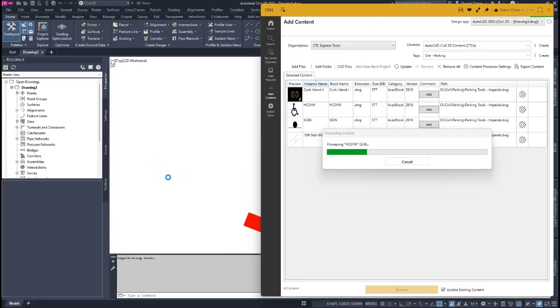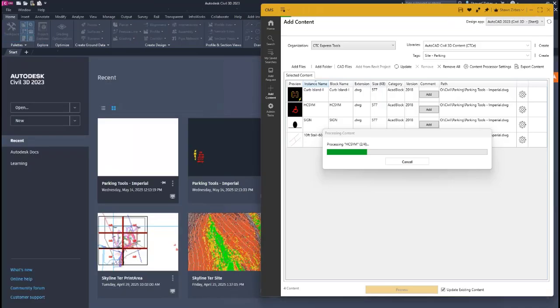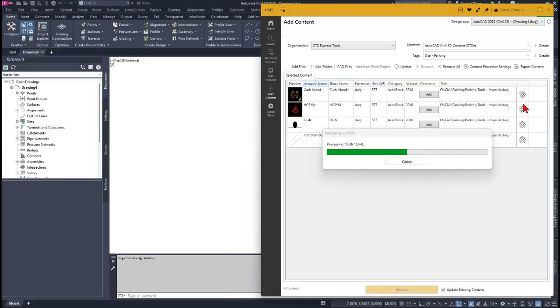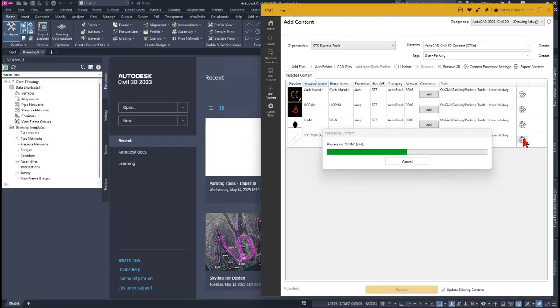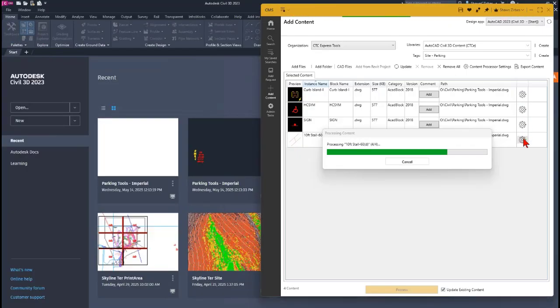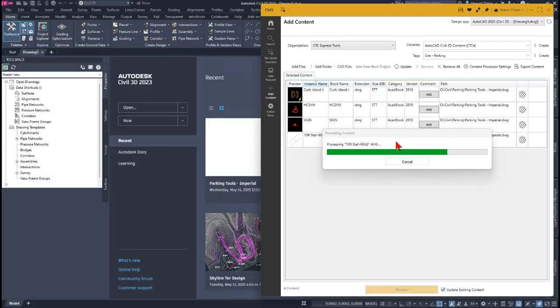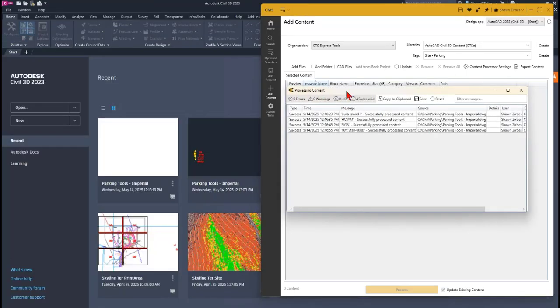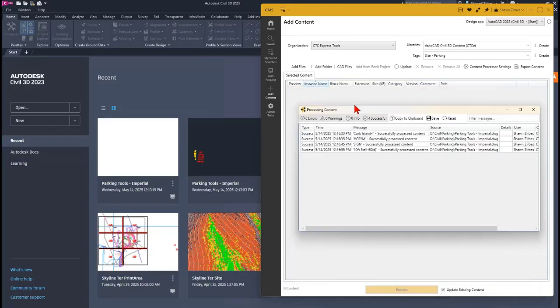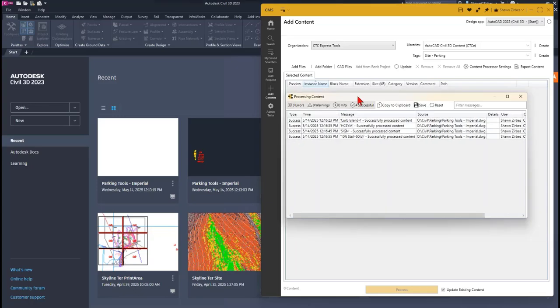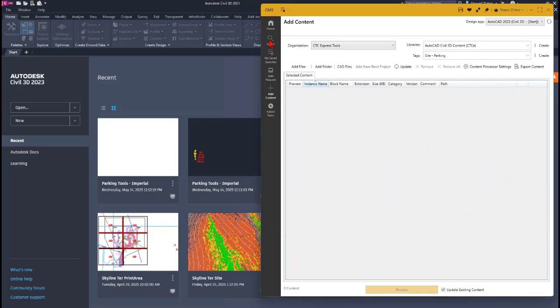And the nice thing is that in that master file, if you already have your content, like a block placed on the right layer, it'll actually pull that in the individual block settings. This is very much like what you do with tool palettes, where you say, put a block on layer such and such, use these explicit properties, scale it in this way, use these options for dynamic blocks. It will actually take each of those blocks, if they are dynamic, and reuse those properties. In this case, all of these were successful, and they now all exist in my library.